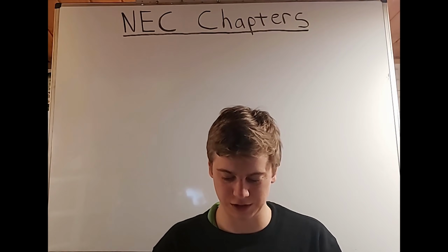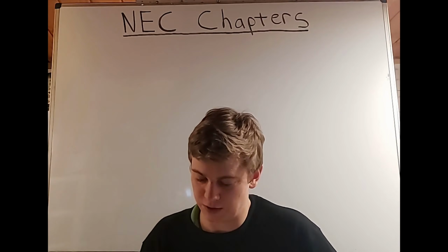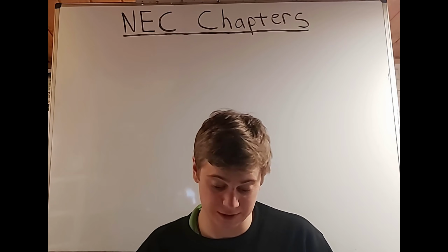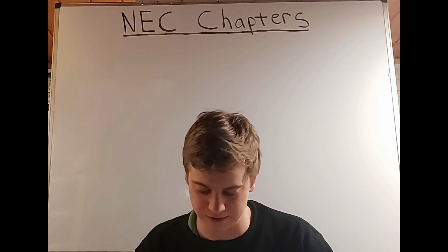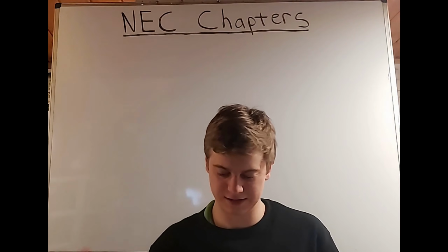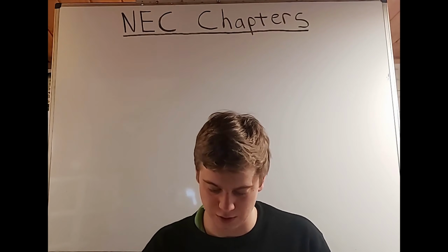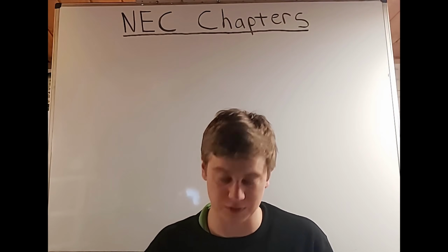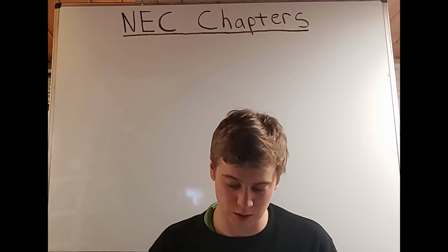B says cooling. It talks about electrical equipment that needs certain airflow to help it cool down. In their words, electrical equipment that depends on the natural circulation of air and convection principles for cooling of exposed surfaces shall be installed in a way so that the room airflow over such surfaces is not prevented by walls or adjacently installed equipment.